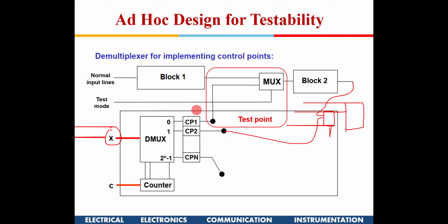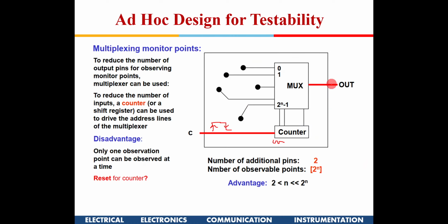So I have one more demux out here, right? And that demux can again be done with a counter. Now this counter needs to be properly synchronized with the system clock. Only then will this entire process work fine, right? It should not happen that when I am giving a counter value of say 8, this 8th output is going to the 8th block, and at the output also the counter is reading 8, and the output is available from that particular block only, right?